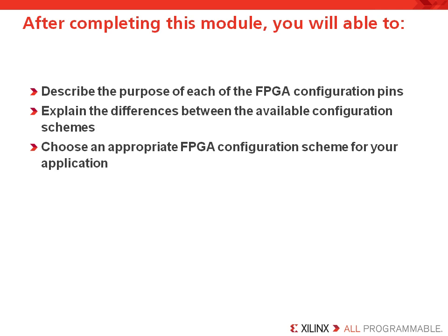After completing this module, you'll be able to describe the FPGA configuration pins. This is essential because the configuration process is relatively automatic after the configuration scheme has been selected, and this is done by pulling the configuration mode pins high or low. You'll also understand the differences between the different configuration schemes that are available to you. From this information, you'll be able to choose an appropriate FPGA configuration scheme.